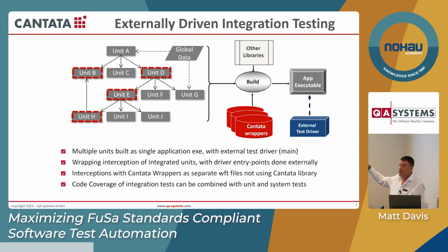Where Cantata can come in this case is Cantata wrappers can be built into that application if you have source code available to test. And that gives you the interception control and invocation at whatever you want to. Those wrappers are separate from a Cantata test script. In a unit test driven by Cantata, they are integrated. And of course, code coverage of integration tests and system tests, and anything that drives the software, can be measured by Cantata and combined.